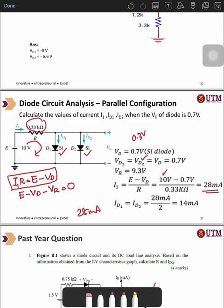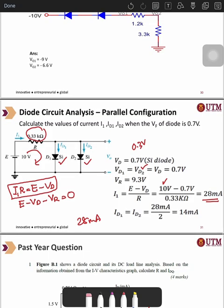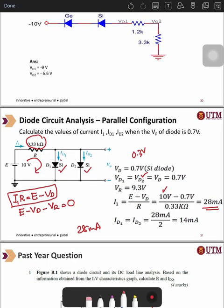When you get the I1, now you can calculate the VR: 9.3. I1 is done. Then ID1 and ID2. ID1 is actually equal to ID2. Why? Because the voltage here is 0.7, the same 0.7 and 0.7, so it is just divided by 2. So 28 milliampere divided by 2. This one is the KCL. So it equals 14 milliampere.